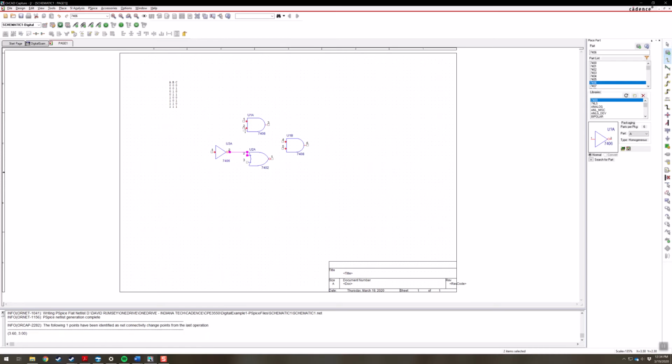So I'll connect that to there. This I'm just going to double click and put some lines out here. These are where the inputs are going to be connected to. And I'll wire that there. And then we need a line out here for the output, just so that we'll be able to put a probe on it. All right, so now I've got my circuit wired up for the most part.